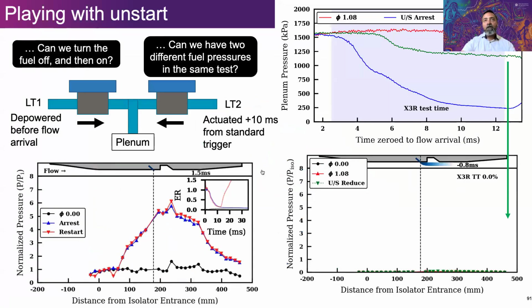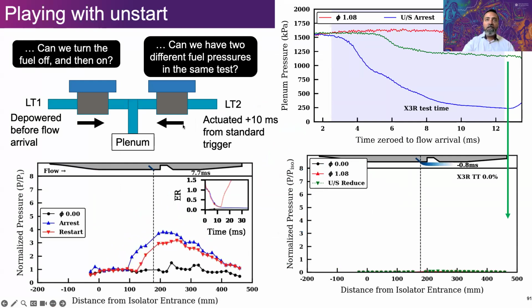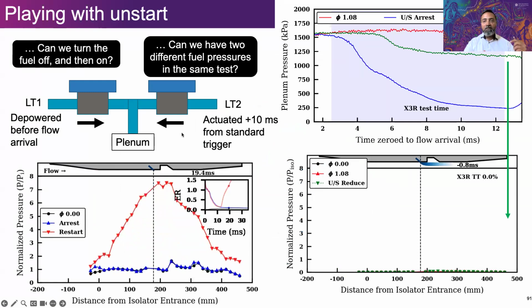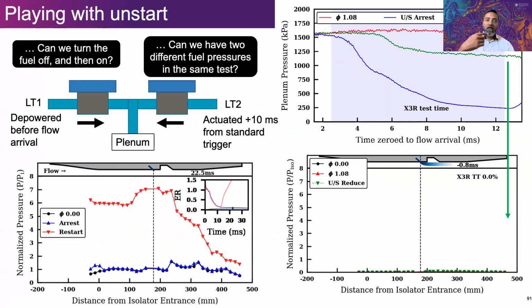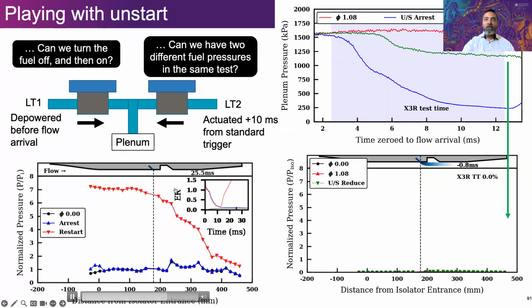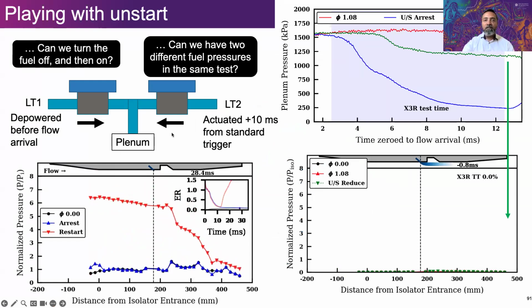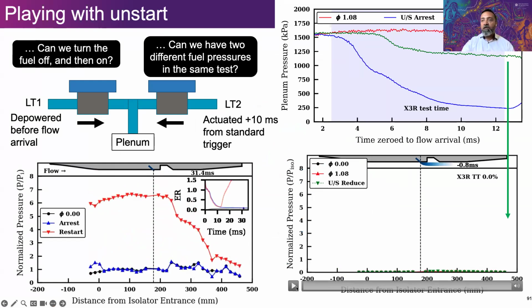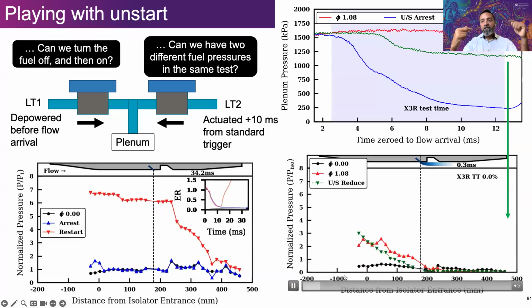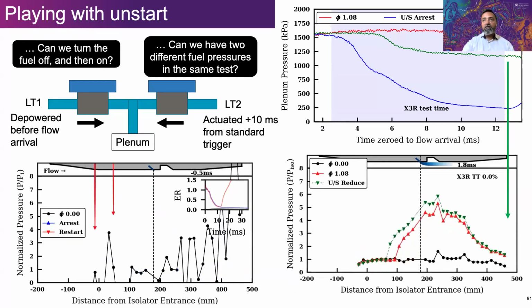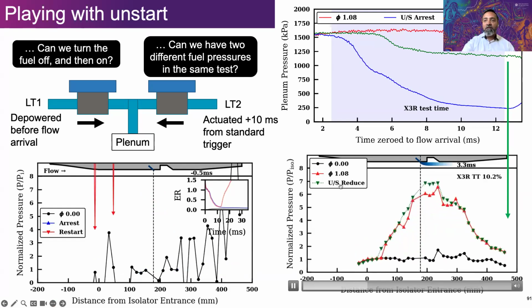Then we attached two valves to control this fuel timing a little bit so that we had the ability to switch off the fuel through one and activate the fuel through another and time it such that in one case we completely switch off the fuel and then restart with putting in the fuel from the other valve so that they're different in time. And in one case, we sort of manage it simultaneously. One is shutting down, the other is kicking up so that we reduce the fueling. We don't know exactly what equivalence ratio we ended up with, but it was enough to prevent unstart.